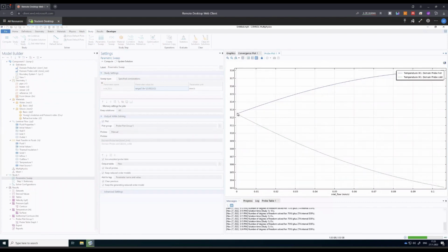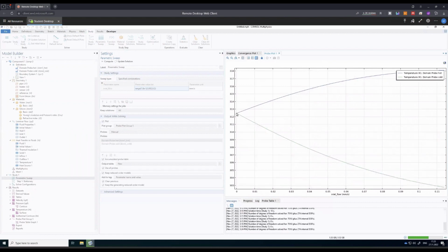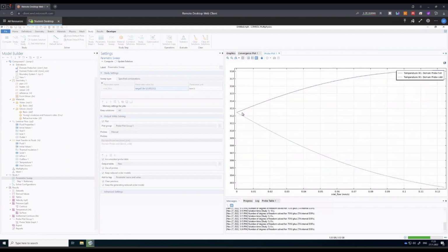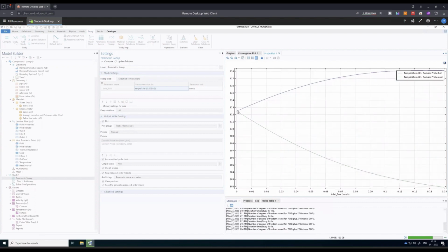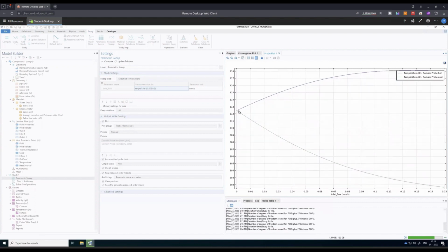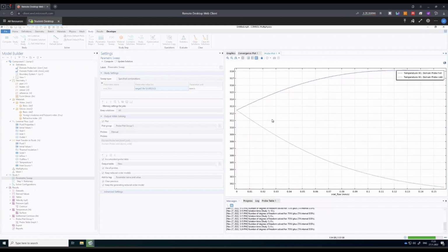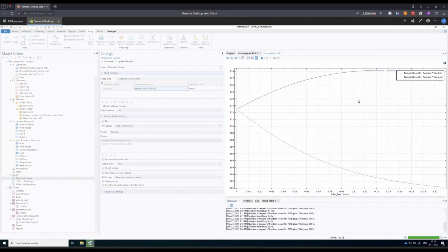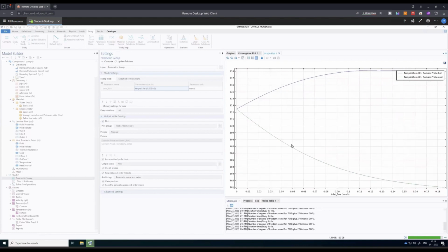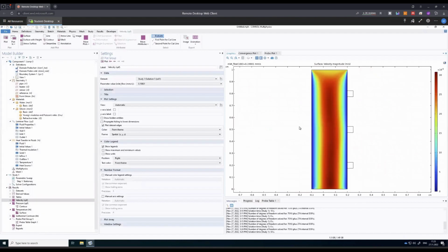When the inlet flow is about 0, there is an absolutely minor difference between the 2 sensors attached to the pipe. But with the increase of inlet flow, the difference increases, but both temperatures behave non-linearly with the change of inlet flow.